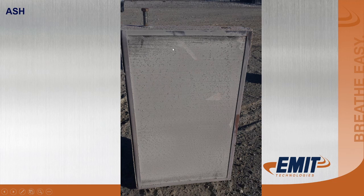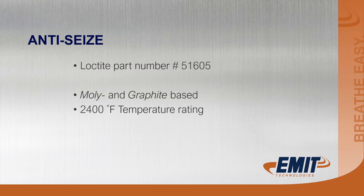You can just take them and blow them out with air and blow that ash back off of there, and then flip them around so the inlet is the opposite side of the buildup. And a lot of times you'll meet emissions just fine with that same catalyst.